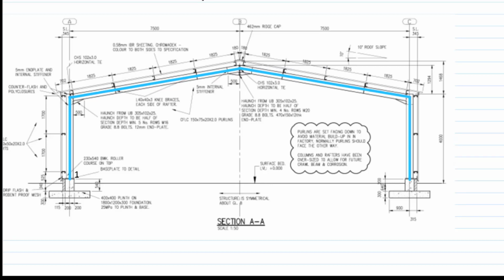So I've drawn blue lines then where we're going to model the beams as beam elements, and now we have to decide how many nodes we want. I mean, if we really wanted a coarse analysis, we could actually just have nodes there and that would be fine. But with all the purlins, it makes sense that we add some extra nodes where the purlins are, or on top, to analyze it.